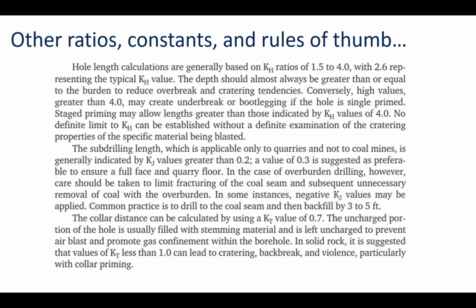In the case of overburden drilling, however, care should be taken to limit fracturing the coal seam, right? So that's why you don't want to do subdrilling in coal. You stop above the coal, you backfill 3 to 5 feet, so that way you're not breaking the coal, you're not getting it diluted into the overburden you're removing. You want to keep it intact.